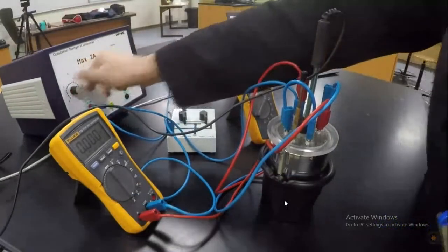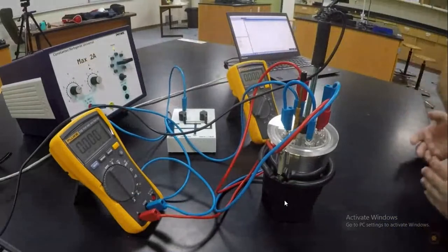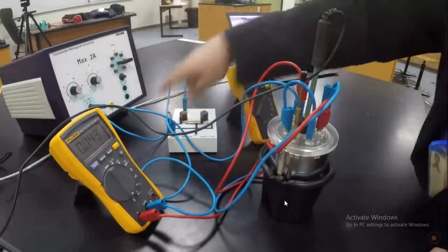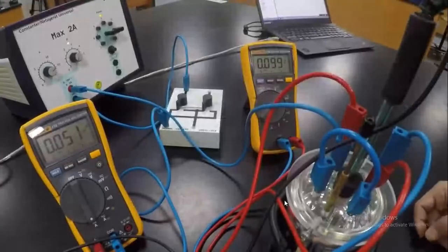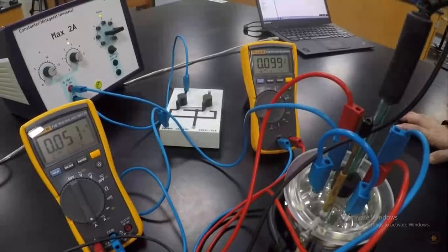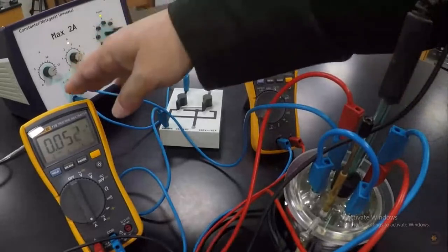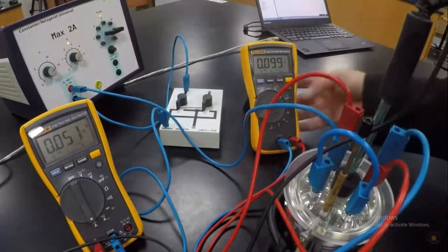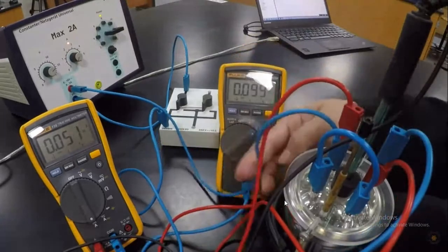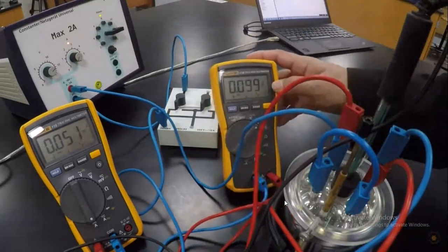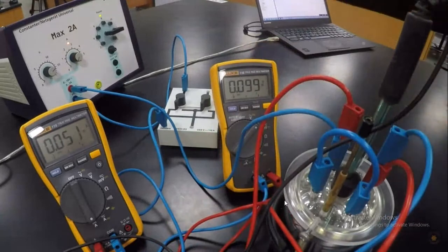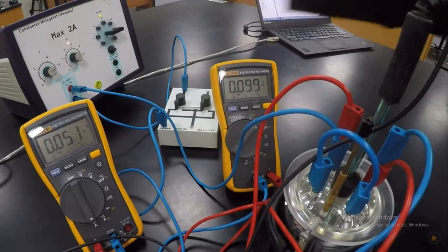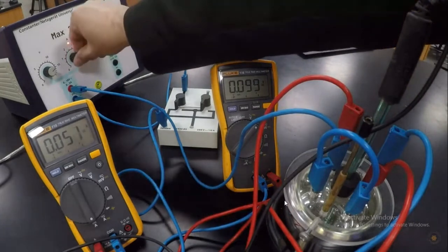Push the voltage, you can go maximum. It is safe as long as the current is at 0. And then switch on your switch. There you go. You should get a small amount of current from your power supply, since your power supply current is set to 0. And you should get a small amount of voltage as well. The next thing that you can do is to increase the current so that you will reach up to 1 ampere.